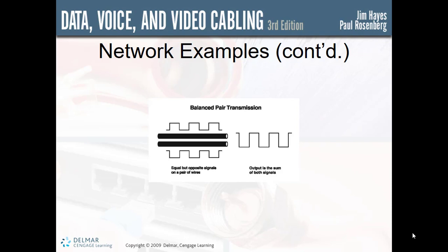At higher speeds, signals are compressed and encoded, and multiple pairs are used for transmission in each direction to allow operation with networks of over 1,000 meg per second. UTP has 4 twisted pairs in the cable, 2 of which are used to simultaneously transmit signals in opposite directions, creating full duplex links. Some of the higher speed networks now use all 4 pairs to reduce the total bandwidth requirement of any signal pair.